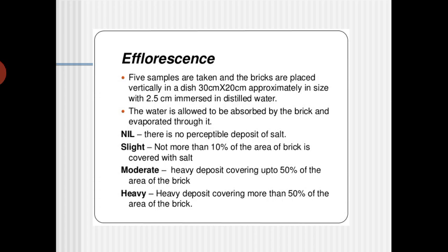I already said, even when you are doing this test, make sure that it is in distilled water. For the previous case, I already said that the conductivity of the water should be less than 100 microsiemens per centimeter.